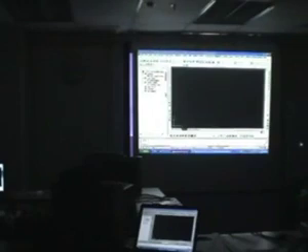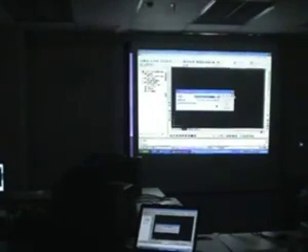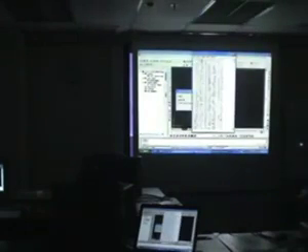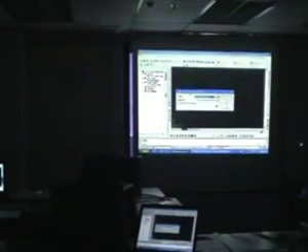And this is where we specify the format of the file you want to import. For Land Desktop, this is the list of default formats that comes with the program. ENZ, for example, stands for Easting Northing Elevation. You've got comma delimited, space delimited. Delimitation just means what separates one column from another. In this case, it's a comma. Sometimes you may come across just a space, or maybe a lot of spaces. So at least you can use space delimited in that case.